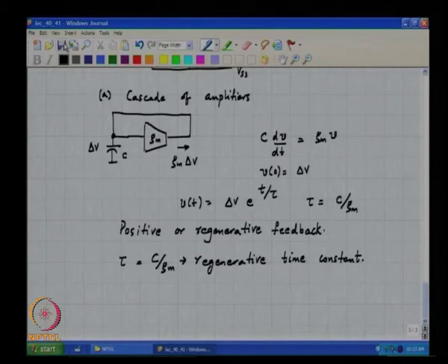Okay. Now, apart from figuring out how to realize this with transistors, we will have to observe that in practice this Gm is going to be powered off of some supplies, correct. So, even though in principle the output voltage should go to infinity, in practice it will be limited either to the positive rail or the negative rail.